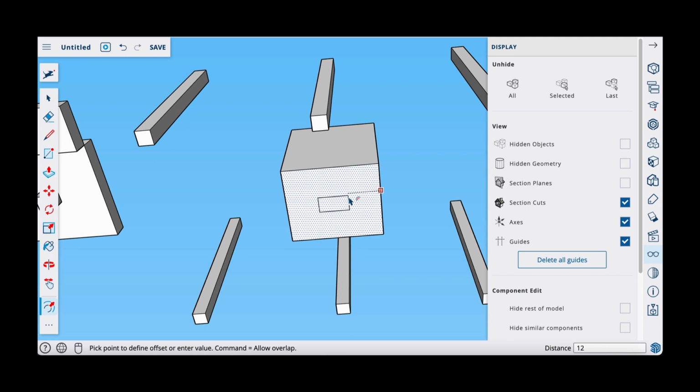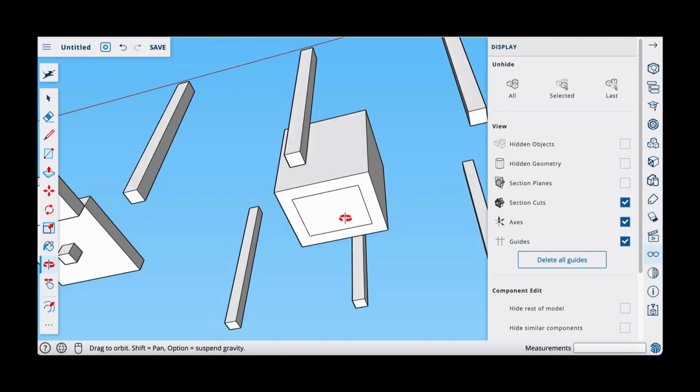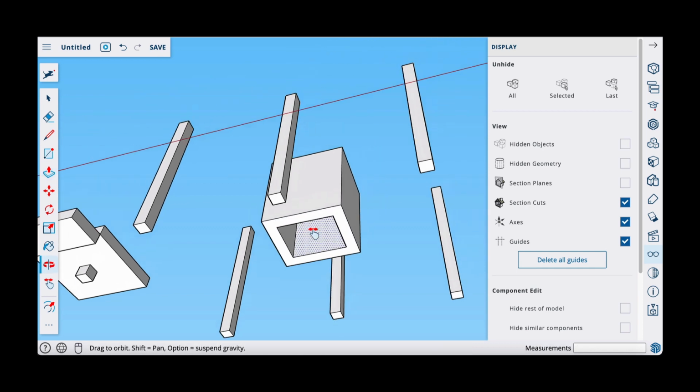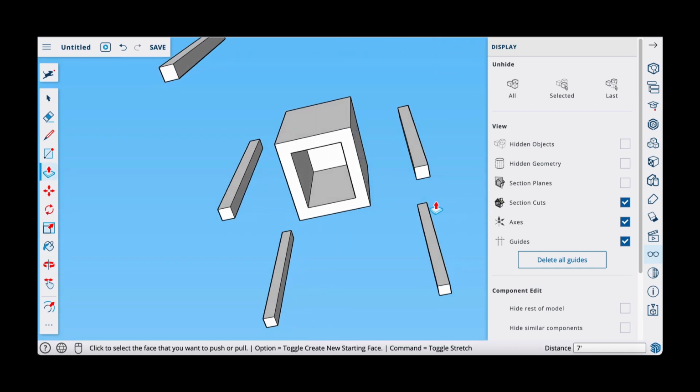And I'll just type 1, 2, enter for 12 inches or 1 foot. Alright. And I'm going to say that the ceiling of this room is also 1 foot thick. So that means I'm going to pull this up by 8 minus 1, which is 7 feet. So I will use my push pull tool. And let me just select this, push pull, click and release, and go up 7 apostrophe enter. Alright, so I hollowed out that space here.